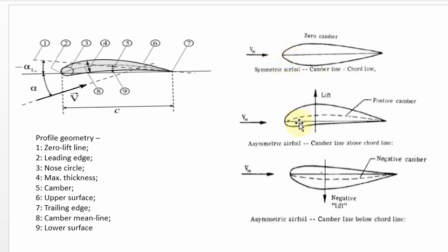But under the same condition here, this is my chord line and this is my free stream velocity line. Even though the chord line and the free stream velocity line are the same line, so the angle of attack is 0, it produces some lift value. Suppose I am using a cambered aerofoil for my design, but I don't want the lift value.